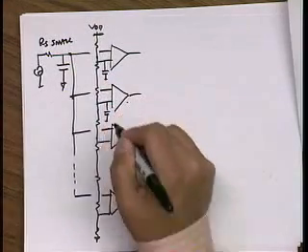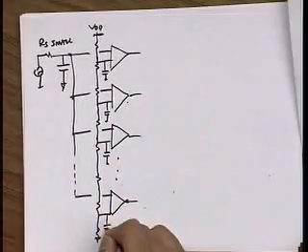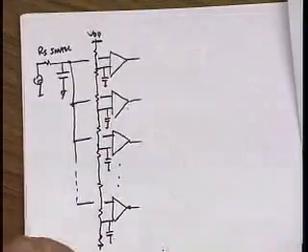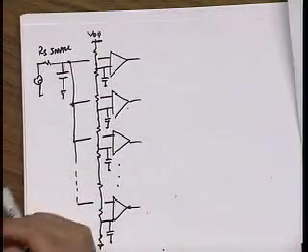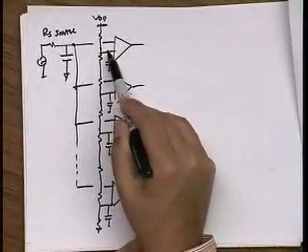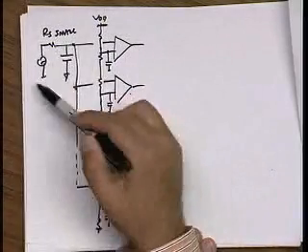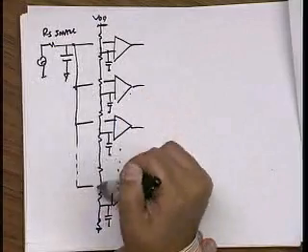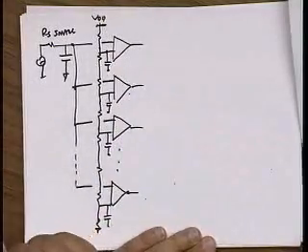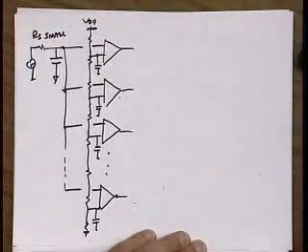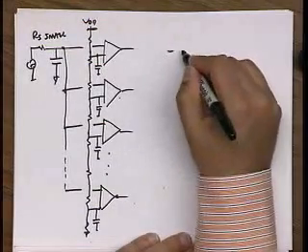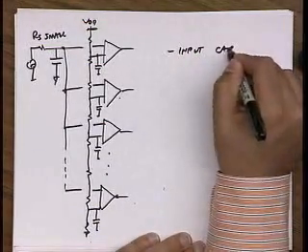I can't make this too small, right? Why not? Current, right? Yeah, I'm going to dissipate a lot of power. So I do care about capacitance because even if I can make my source impedance really small, I'm limited to how small I can make this resistor string, and that may end up being the speed limitation. So here, in this application, I would care about input cap.